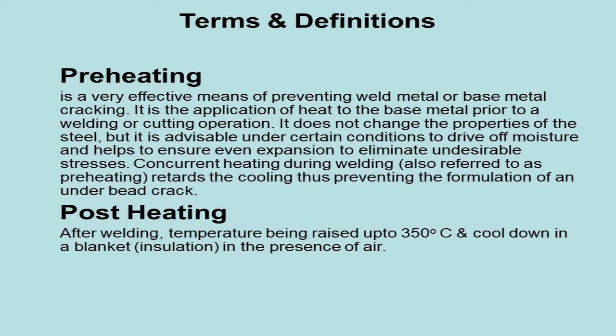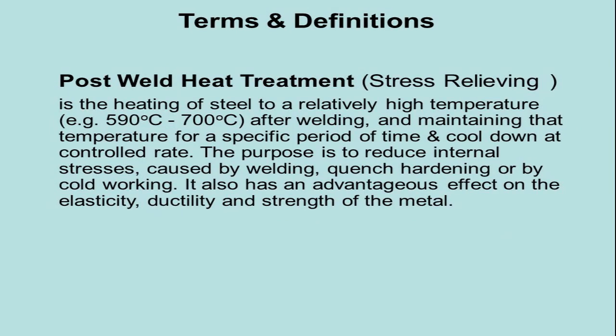Post-heating. After welding, the temperature is raised up to 350 degrees centigrade and cooled down in a blanket, insulation, in the presence of air. Post-weld heat treatment, stress relieving, is the heating of steel to a relatively high temperature.